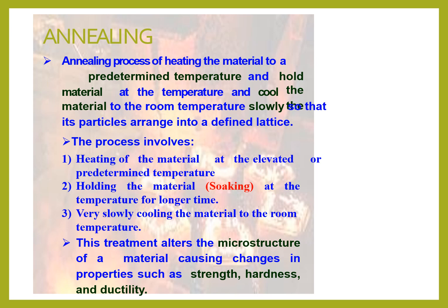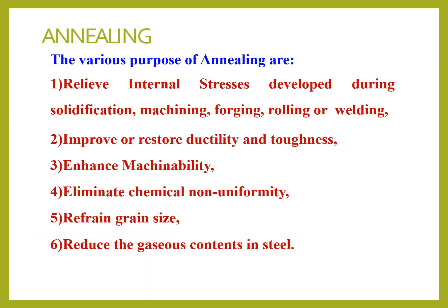So it will give good properties, that is strength, hardness, ductility. It will relieve the internal stresses. So all these properties will change. This is called annealing.